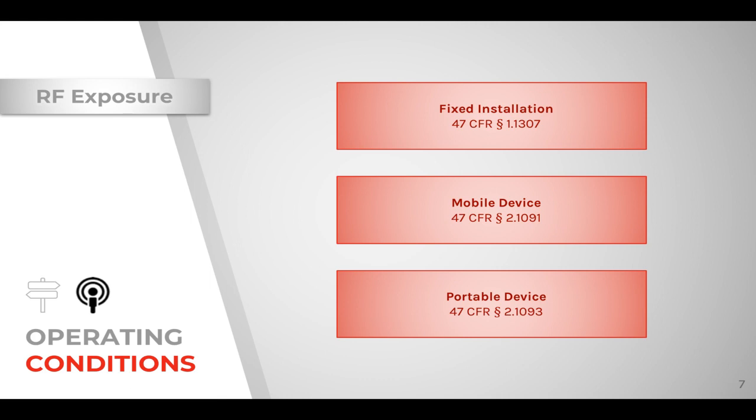When I mean separation distance from the human body, we are talking about the antenna, or basically the radiating structure of the device. For example, if a device is outside, like a base station, you would get exposure in a far field condition. Your whole body would get exposure, but it would be in a far field condition. So in that case, we use MPE evaluation.